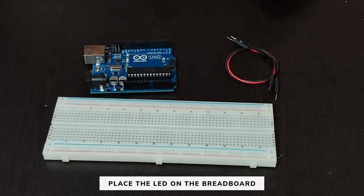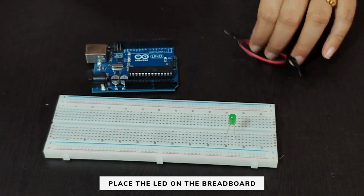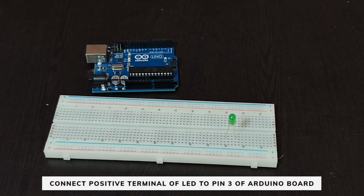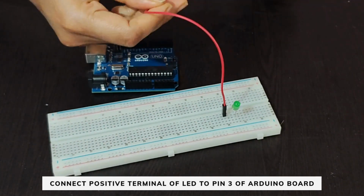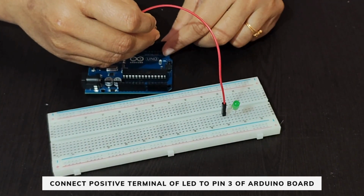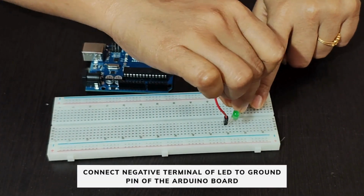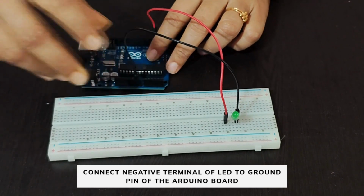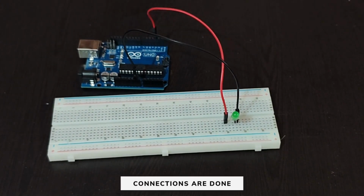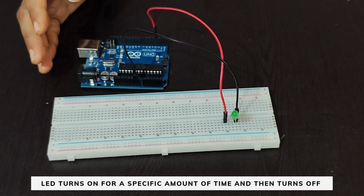So we will place the LED on the breadboard. Connect its positive terminal to pin 3 of the Arduino and the negative terminal to the ground pin of the Arduino. Our connection is done.